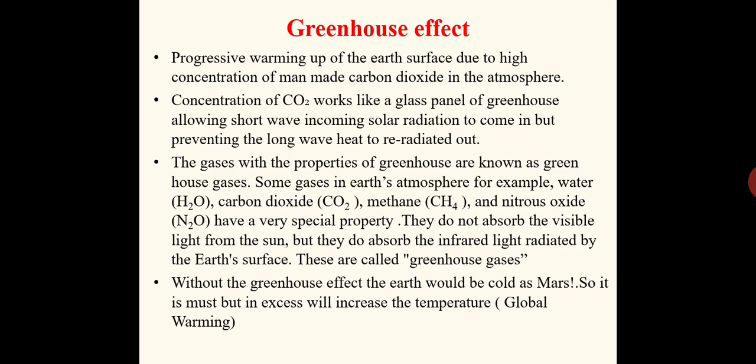See, the same principle is utilized in solar collectors. The radiation which passes through the glass panel will not be reflected there itself, since it has the shorter wavelength. But once it reaches the absorber plate, the plate will absorb this radiation and re-emit it. While re-emitting or reflecting, the wavelength is increased. Once the wavelength increases, it cannot pass through as it came in. So it is actually trapped inside that collector. That is what is happening. The same effect is happening in the atmosphere also.